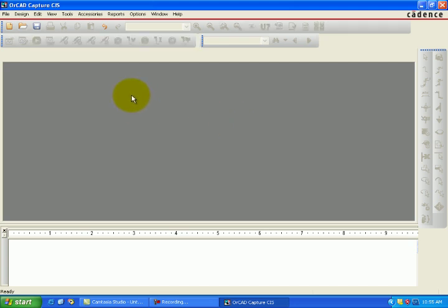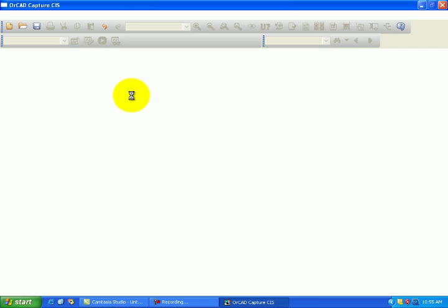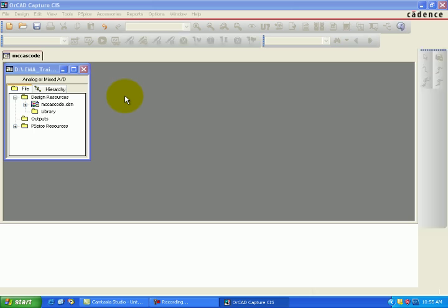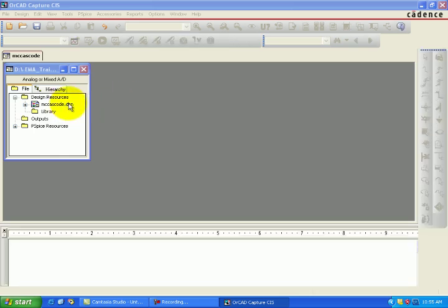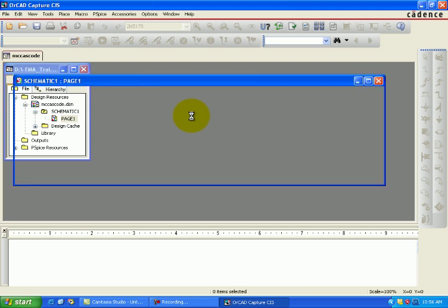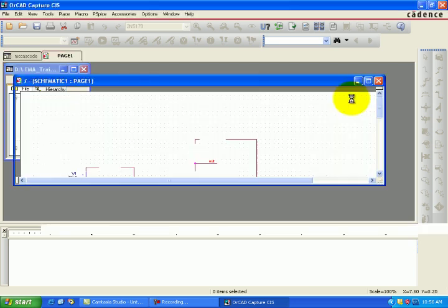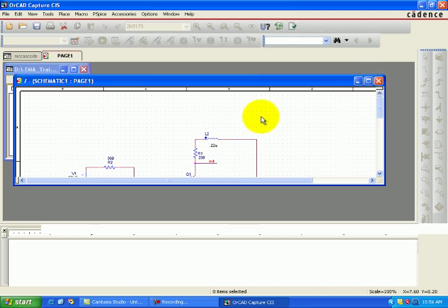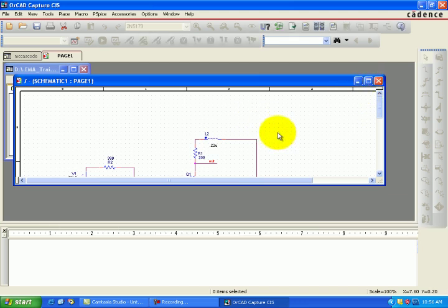First of all, open the circuit. In PSpice for the Monte Carlo analysis, we have four functions: flat, Gaussian, bimodal, and skew. The Monte Carlo analysis is like a key to the tolerances and the distribution in our circuit. The standard and the custom measurements are associated with the simulation profile.